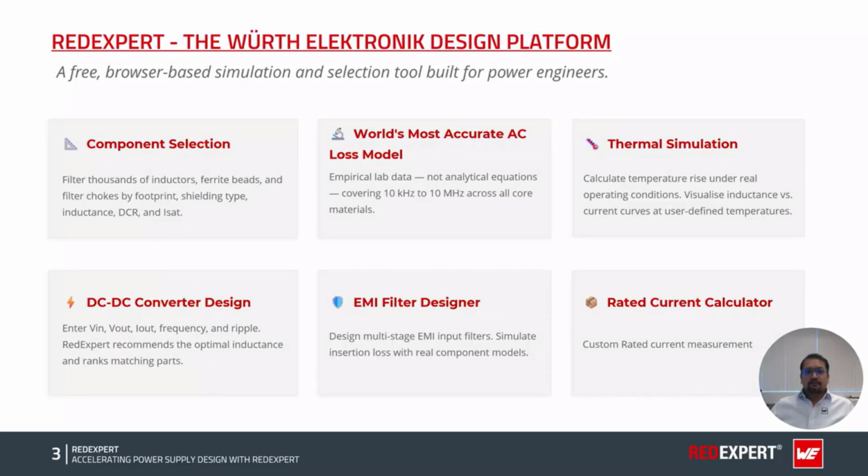REDEXPERT is Würth Elektronik's free browser-based design platform built specifically for power engineers. No installation, no license fees, just open your browser and start designing. At its core, REDEXPERT does several things. First is the component selection. You can filter through thousands of inductors, ferrite beads, filter chokes, common mode chokes, based on the footprints, shielding types, inductance, DCR, saturation current instantly.